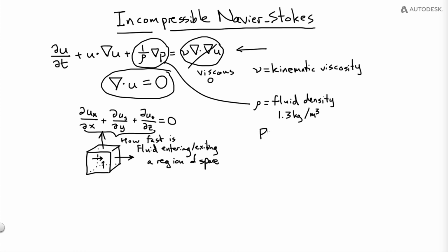And P is the pressure, which I didn't mention on the previous drawing about channels that we track. It does turn out to be a channel that we use internally, but it's really just used internally to satisfy the constraint here, that the fluid maintains its volume. So pressure forces act to prevent the fluid concentrating inside one cell or leaving another cell. We figure out the pressure that will even things out.